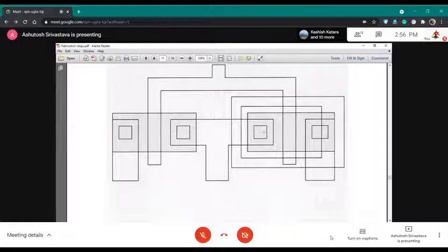You should understand. So this actually is giving you the layout diagram for a CMOS configuration where you are having a PMOS and a NMOS. This NMOS drain and PMOS drain are connected to each other as well as the output.